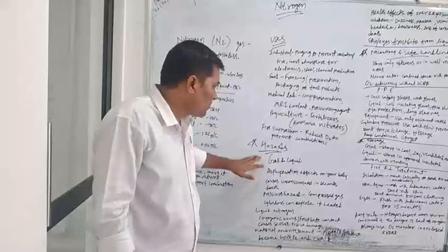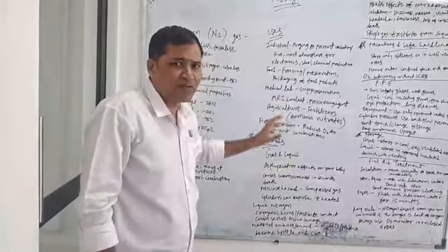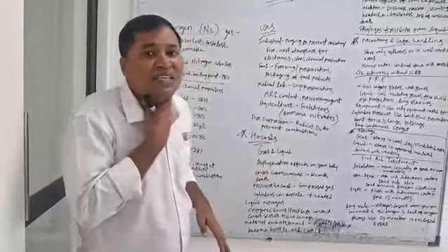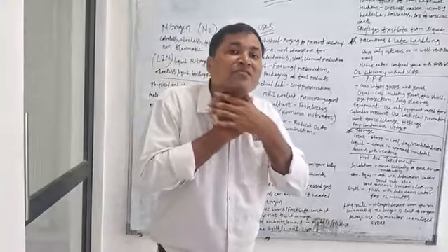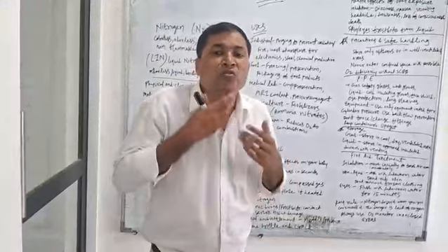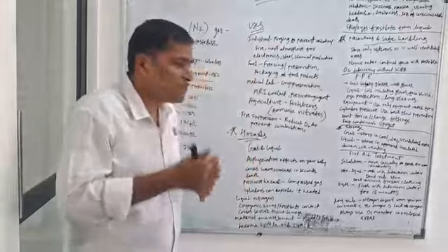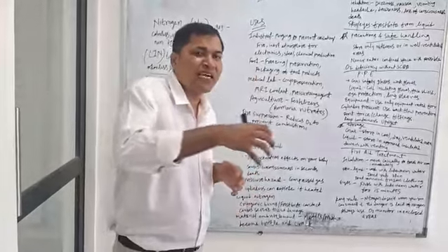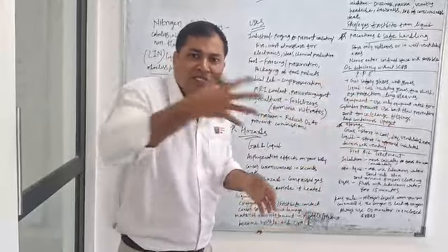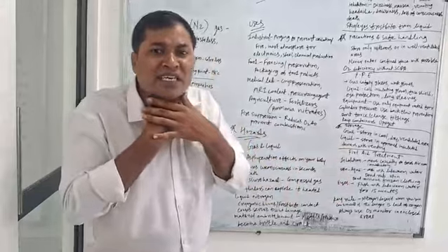There are different kinds of hazards, like gas hazards and liquid hazards. There are two types of hazards in nitrogen. For gas and liquid, you will feel an asphyxiating effect, which makes it lethal for humans. If you are working in that zone, the oxygen level goes down, and you will feel the asphyxiating effect. If the oxygen level goes down while you are purging with nitrogen, never stand in the same area. It is better to go out immediately. If you are purging nitrogen in a container and you are standing there, you will feel the asphyxiating effect.